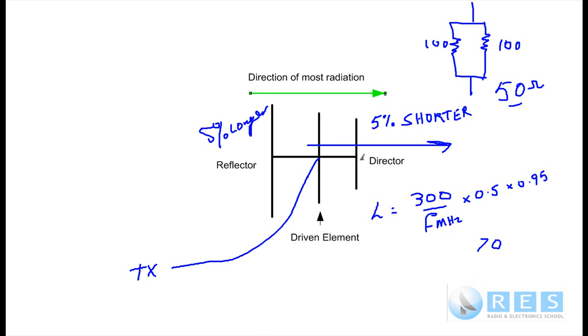And our impedance of 3 dipoles in parallel is going to be roughly 3 into 70, whatever that is. And the more elements you have, the lower the impedance is going to be. And so we normally have some sort of special matching device there to match to the 50 ohms of our feed line. The typical matching device is called a gamma match, but again, you don't need to know that for the standard, and I don't want to prolong this course for you.